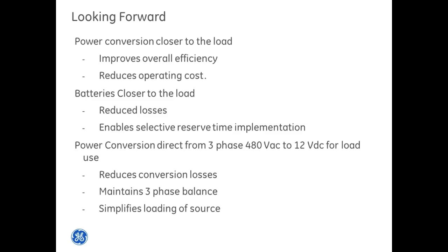It also inherently maintains three-phase balance if you have a true three-phase rectifier feeding the load. What this does is allows you to make sure that your UPS or other backup system is balanced from the standpoint of phase-to-phase loading.